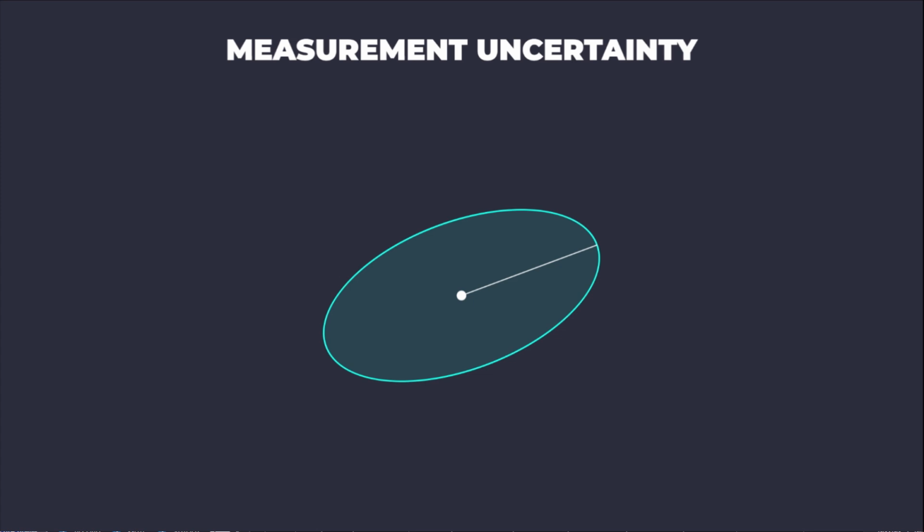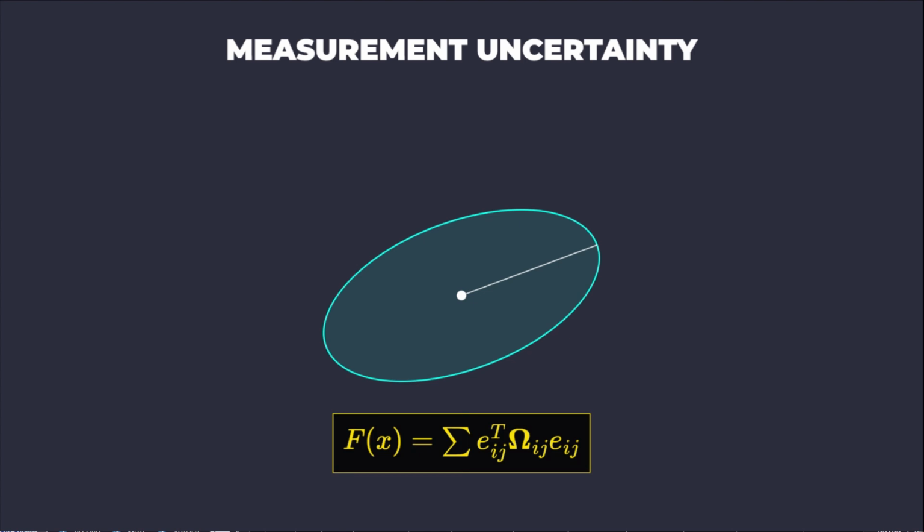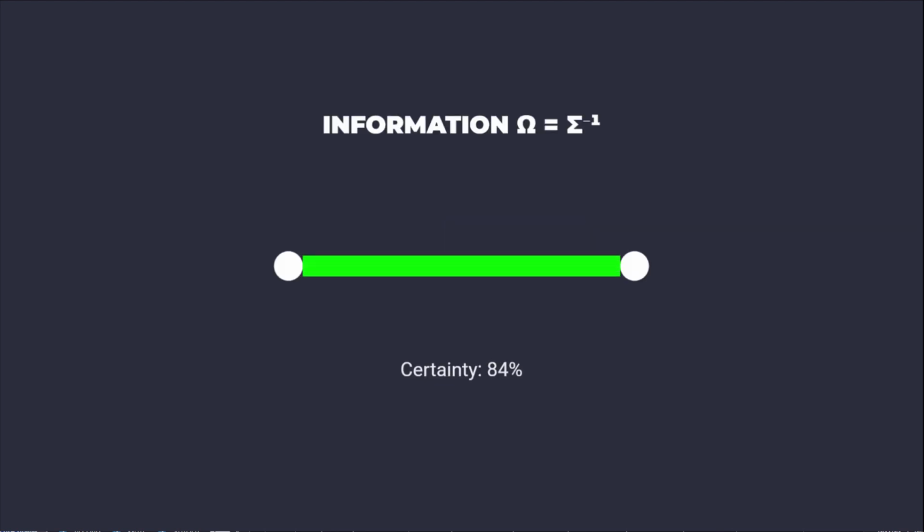The measurement model provides the mean and covariance of the relative transformation, defining the strength and uncertainty of the constraint edge. This structure naturally leads to a sparse Hessian matrix during optimization, crucial for computational efficiency. GraphSLAM minimizes a global cost function, often formulated as the sum of squared errors weighted by the information matrix. The error term, or residual, for any constraint edge is the difference between the measured relative transformation and the transformation predicted by the current estimates of the connected poses.